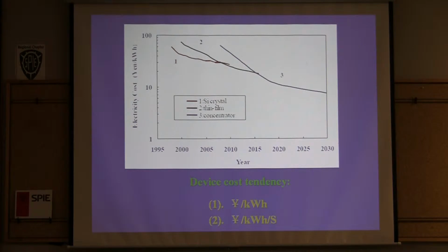Also, typically, you consider not just how many dollars for how much energy, but how much energy per square meter, because the area on the Earth is limited. If you get 10% efficiency or 50% efficiency, this means 5 times the area; the smaller area can get more energy. That's more important. Not just cost per dollar, but how much energy you get per square meter. That's another factor.